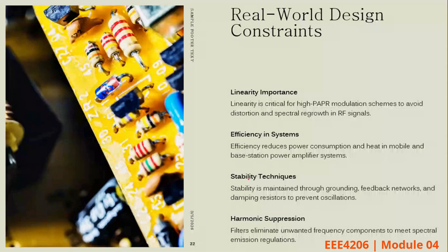You need it to be linear, but you also want high efficiency to minimize power consumption and heat generation. So we also need to ensure stability, as I talked about, so that the amplifier does not oscillate under different load conditions. You need to do what you call stress testing. You test your amplifier in different conditions to ensure that it remains stable in all conditions and works well.